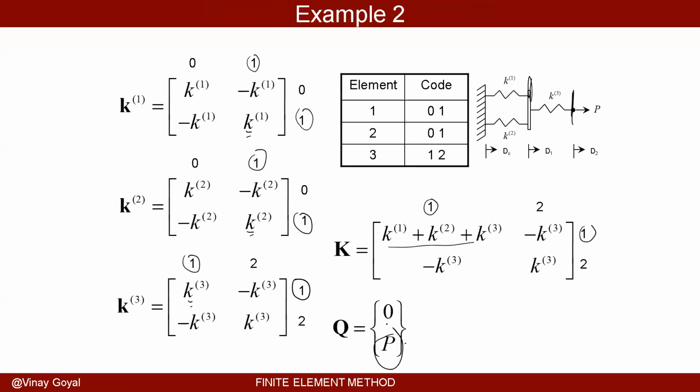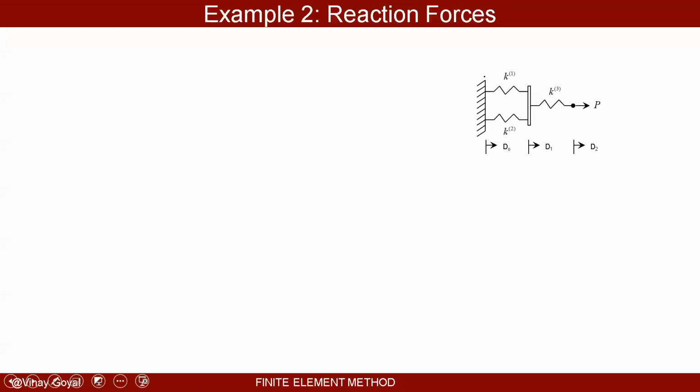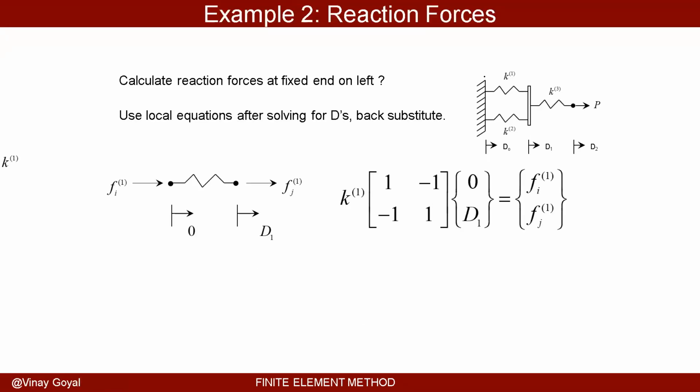How can you calculate reaction forces once you have all this information? Say I want to know the reaction forces on this end. Like what is the reaction force there? What you can do is solve for the deflections first. So you solve for these deflections, and then you go to the local element system for element number one, for example. Element number one is this one.